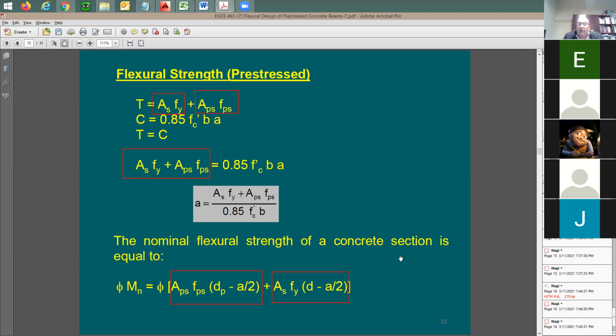This depends on the way that you want to design it. Some people would say, no, I'm going to keep the formwork in there. I'm going to keep the beam short. I'm going to cast all the concrete. And then after that, I'm going to apply the post tension while the beam is supported on the formwork. So in this case, the amount of rebars here, I can just add something for the shrinkage and for the cracking. It doesn't need to be a lot. So this is going to be fine. I mean, it depends on the way that you want to design your beam, if this makes sense.